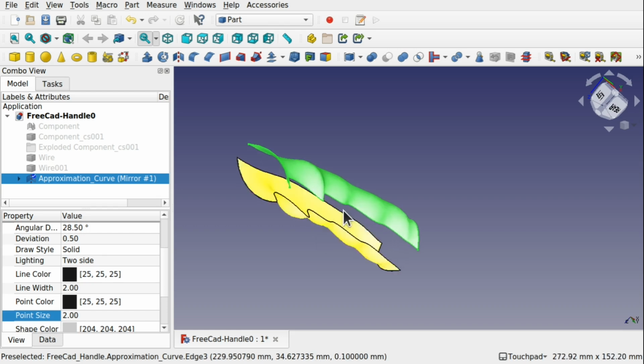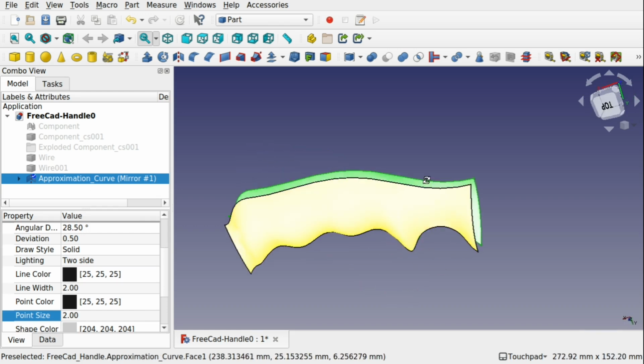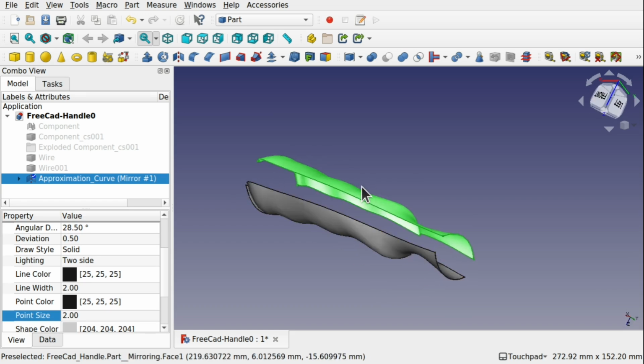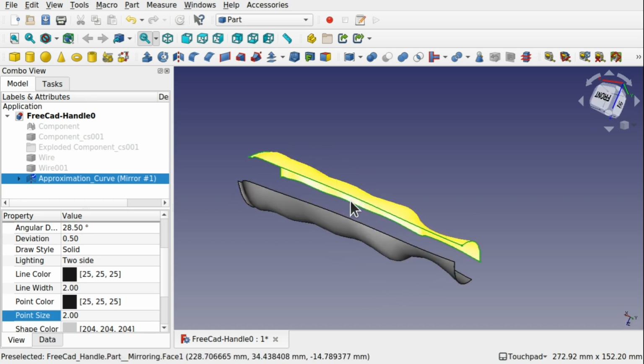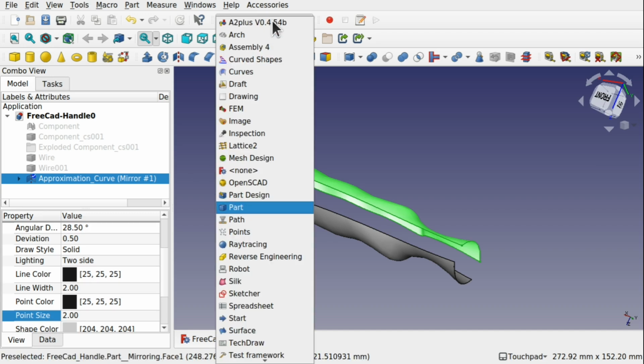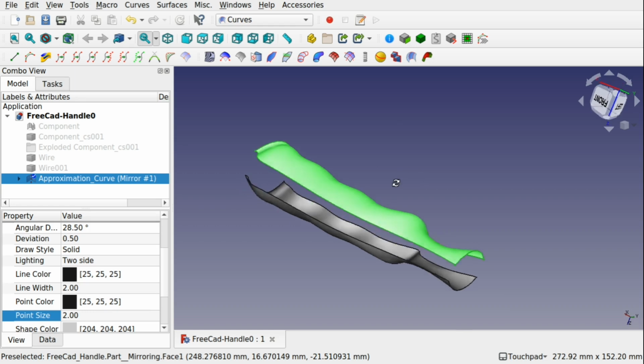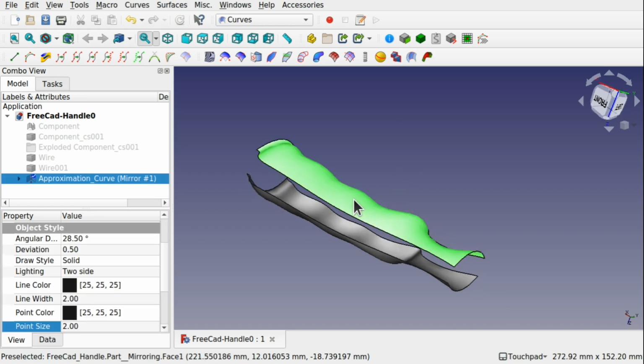We've now got this surface here. So we've got the two surfaces with space between, so I can create the surface across here. To create the surface across here, I'm going to use something called a blend surface. So we come over to the curves, and what we're going to do is click on one face and we need to click an edge.